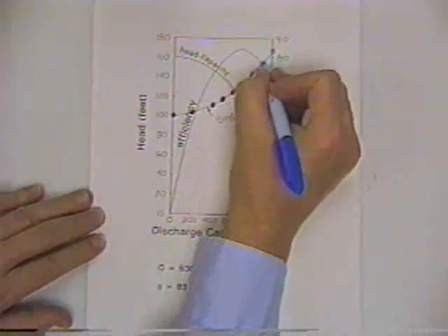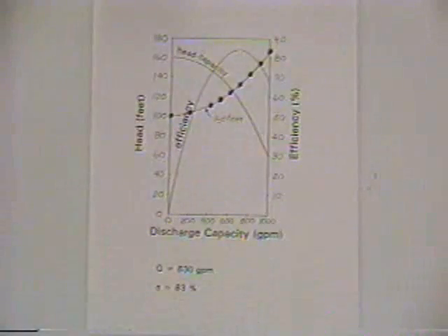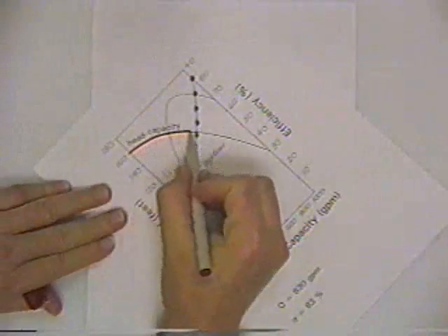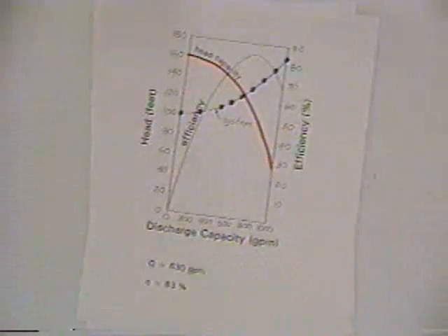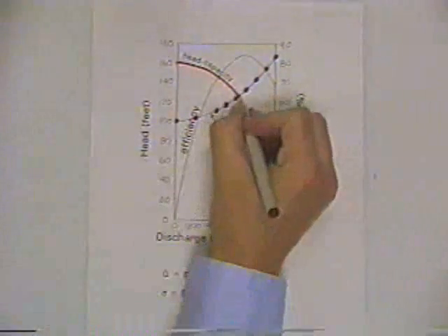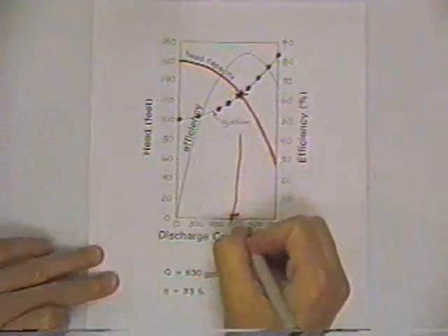And those points represent the system, taking the concepts that we've used in other examples just a little bit further. And then the pump itself is characterized, and this would not be computed, this would have to be given. It's determined in a laboratory. And so what would the discharge be? Well, both of those are good relationships, and this is the point in which they're both valid. And so that point would set the discharge rate.